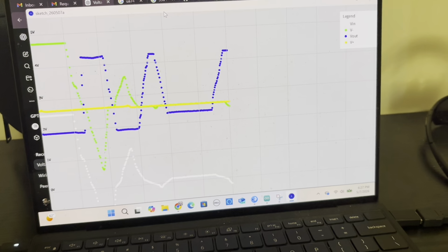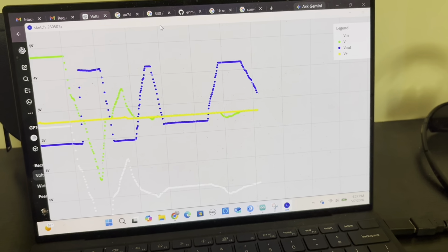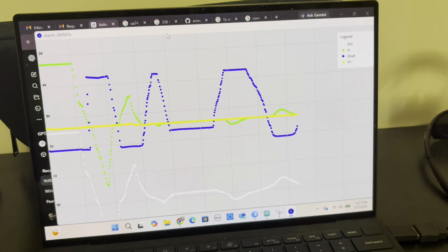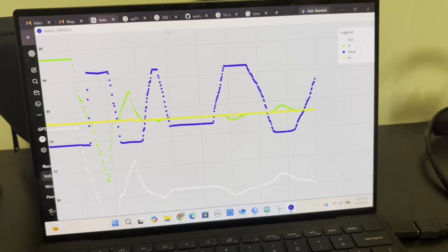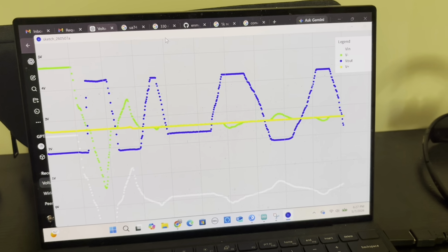Here's my inverting circuit. As you can see, when Vin decreases by a little bit, Vout increases by 10 times more, and vice versa. The Vout is constrained between 1.8 volts and about 4.2. I think this is because of limits in the hardware.